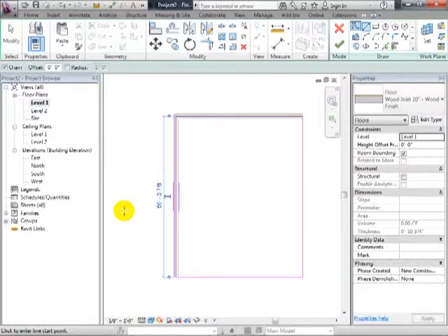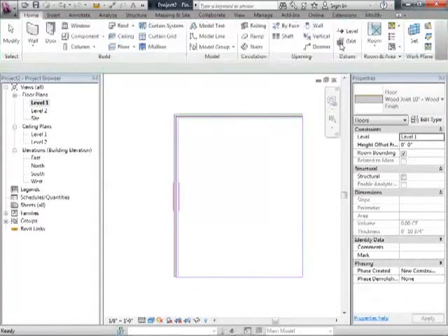What you can do when things don't join together is use this fantastic tool called the trim tool. The trim tool will let you click on two different lines, and it'll bring them together and form a clean intersection for you. So the trim tool is your friend when you're doing these boundaries because it's the cleanest way. Got it? No worries. Now when you get done drawing your floor, click the big green check mark to finish the floor.